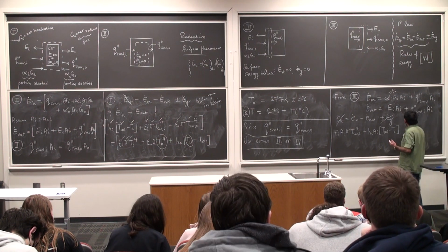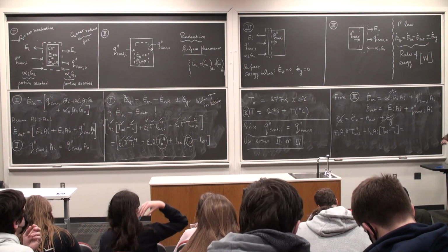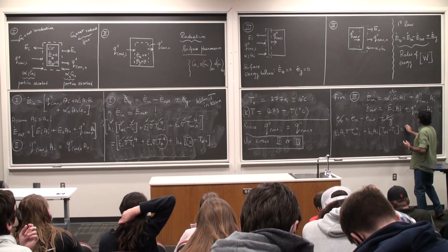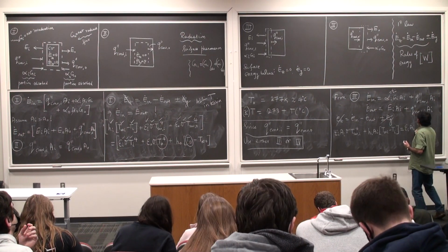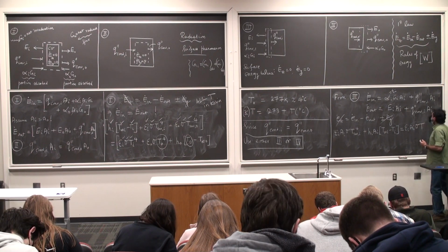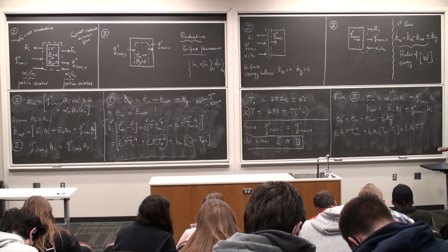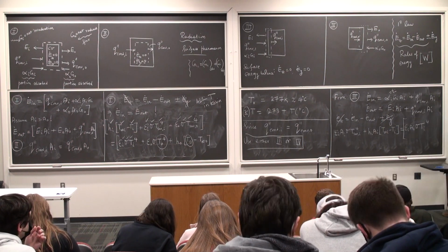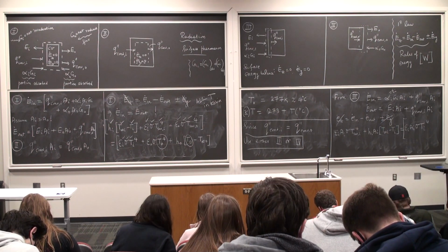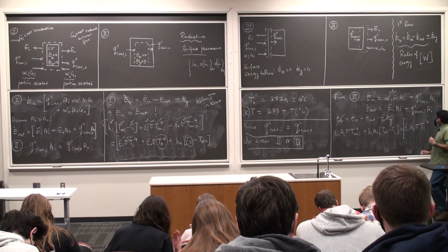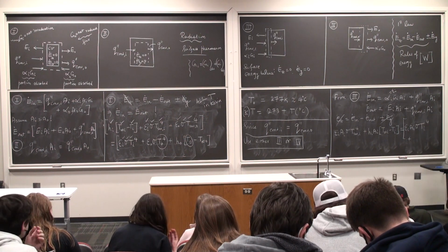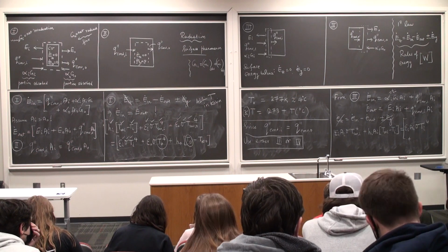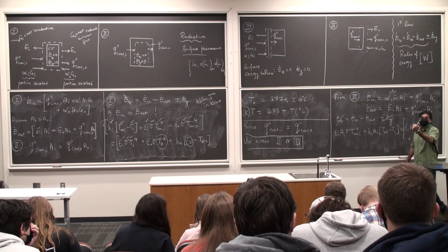This is equal to E I A I, which is epsilon I A I sigma T I to the power 4, plus conductive heat transfer. Steady state conductive heat transfer in this case is taking place from the left side to the right side.